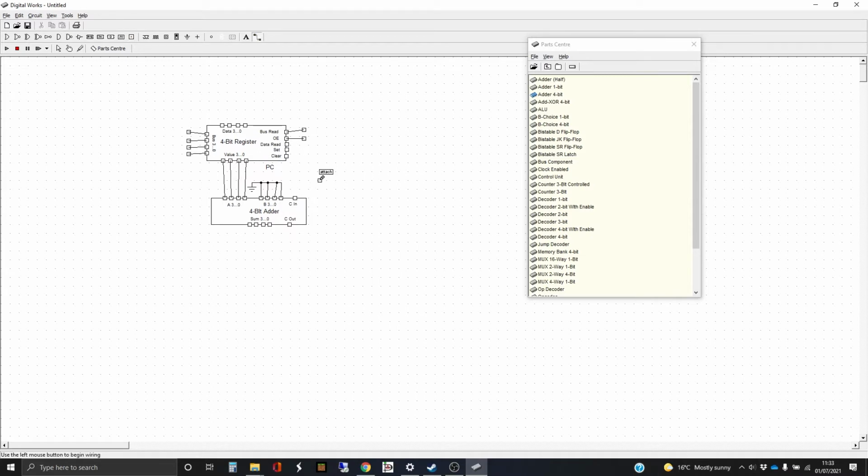And then we're going to link up the cin, and on the output on the control unit, we call that inc, which means it's going to be high if we want to actually do the increment, which is most of the time. But if we've done a jump, it's been set to low.